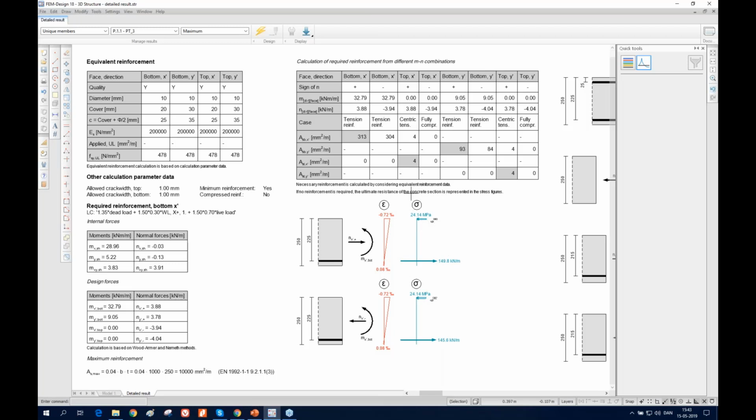The stress is the upper part of this cross section, and here you have what the concrete takes, and here is the reinforcement which takes the tension. You can see this upper part is shown in megapascal, and this one is shown like a force. This one we have done so if you wanted to do compression, it was easier to find the equilibrium this way. And here, as you can see, it says the tension reinforcement.